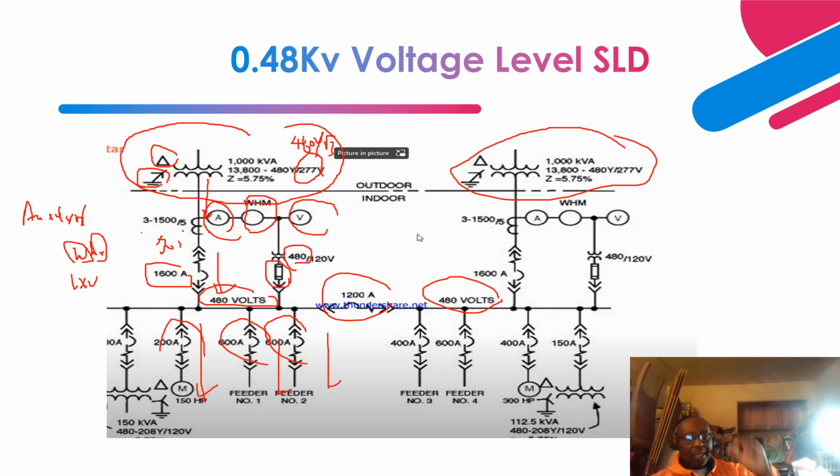Okay, so you can even scale the voltage down to a much lower voltage. You can even go from this level to another transformer. As you can see over here, right? There's a feed that goes to another transformer that steps the voltage down from 480 volts to 208 and 120. So that is when you need those voltages for a power panel. So that is when building facilities come into play. You need a power panel at voltages of 208 or 120 volts. Commercial buildings. So that is when you need to step down these voltages, right?